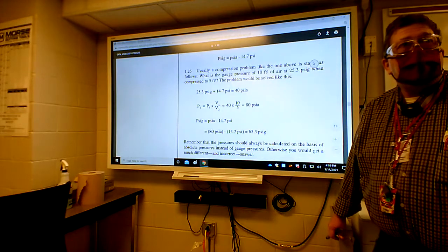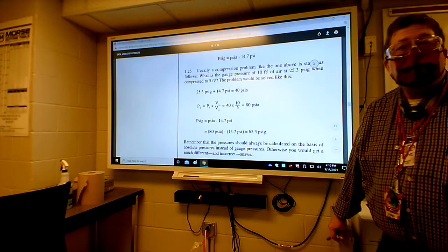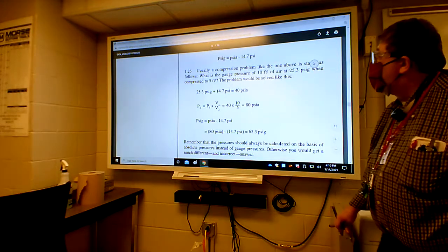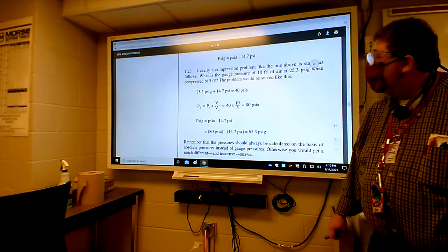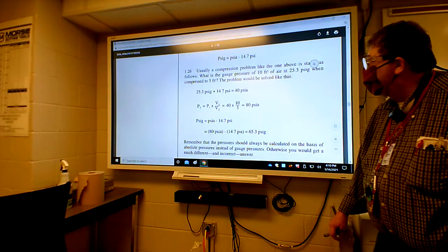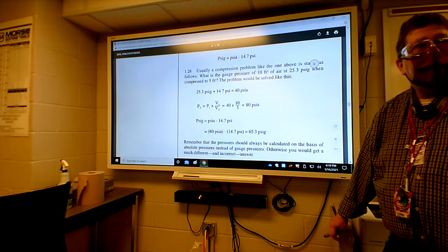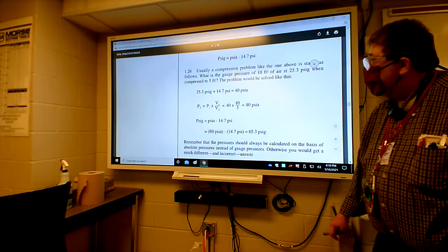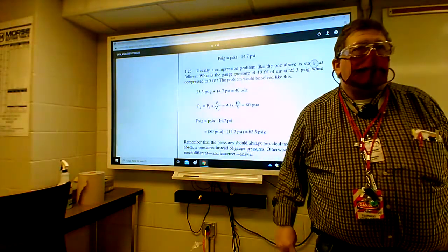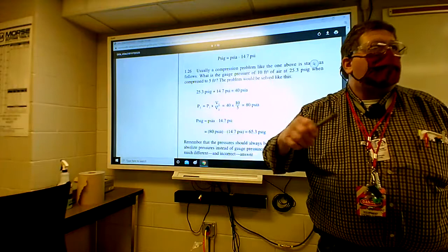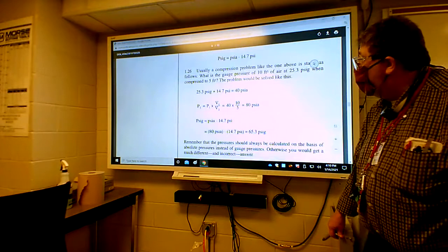Are we done with the equation or not? Or do we do something else? You've got to go back from absolute to gauge pressure by doing what? You've got to subtract out the 14.7, yeah, to get you back to gauge pressure. And what that does is it nulls out the pressure of the air. It's like it's recalibrating your gauge to subtract that part, to give you what a regular gauge would read.